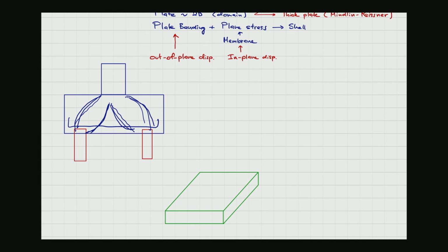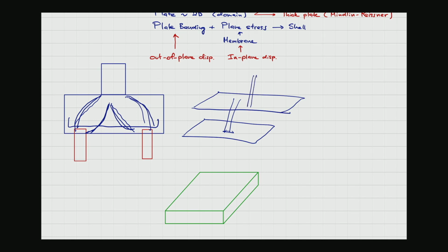Mostly people don't go for elasticity using the continuum and run a full-fledged finite element analysis. So the Timoshenko beam was used, and the thick plate was also used for the design of the foundation. If it is just a simple foundation, then a beam element like the Timoshenko beam might be used. I can see some design offices use these techniques.